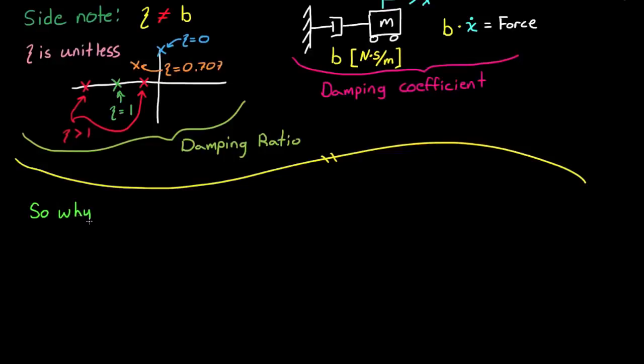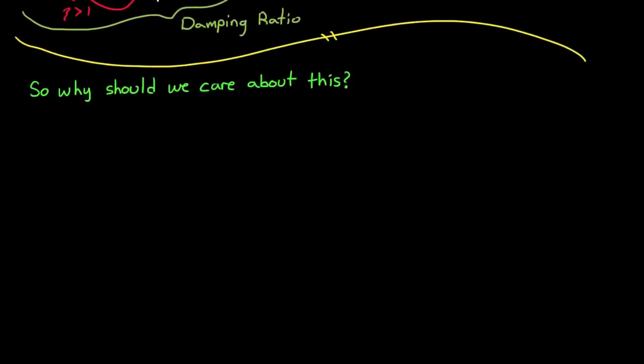So you might be asking, why did I explain all of this information to you instead of talking about the root locus method like the video title says that I should? Well, because it's important in understanding the usefulness of the root locus method. Control engineers have to design control systems to a set of requirements. And a lot of the time, those requirements come in the form of damping ratio, exponential growth or decay, or natural frequency of the system.